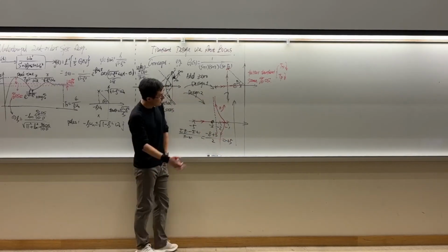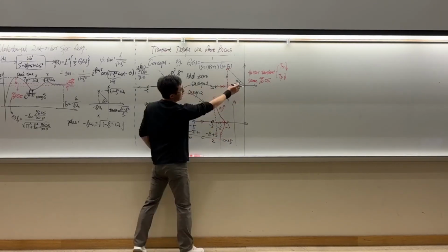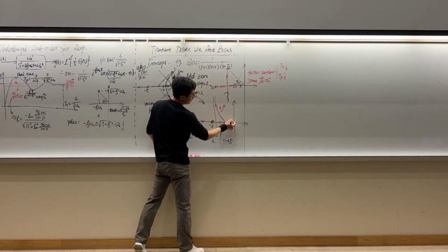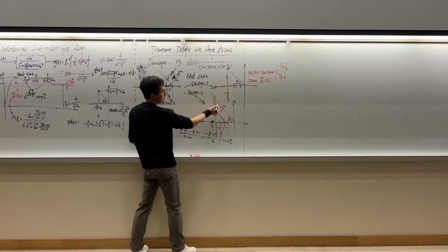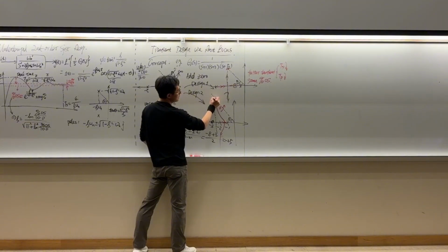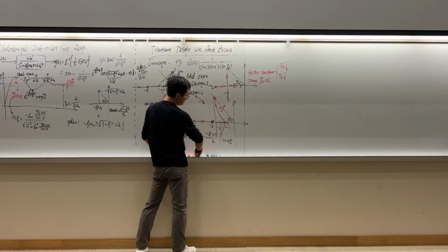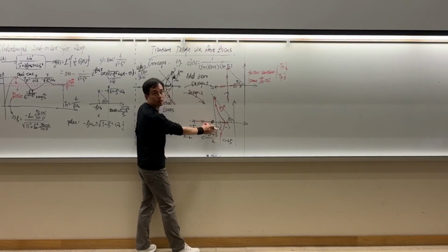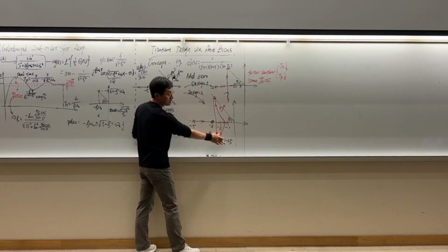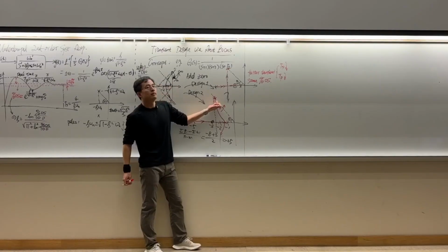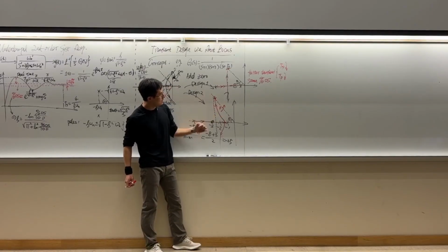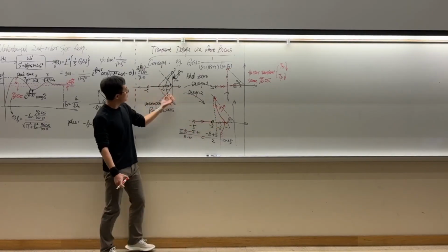like this. Again, you can design, for example, I want the same kind of percentage overshoot. So I want the same design angle. I will draw this line, which will have the desired theta. And then I can find the intersection point. This is my desired closed loop pole. There will be another one in the bottom. I will just draw this part. You can finish the remaining part. Right? So you can have your closed loop design to be like this, which compared to this one, it's still